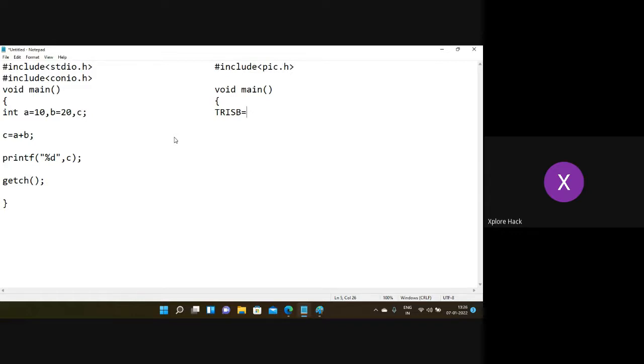To make the machine understand that, we are going to give 0x00. So if you use the number 0, this microcontroller can understand that the 8 pins which are connected with port B should act as output. Instead, if you use F, this microcontroller can understand that here it can use